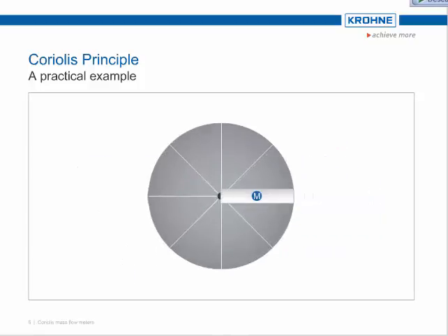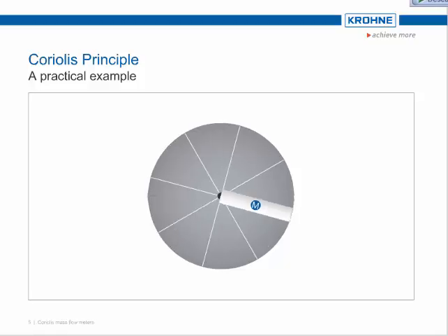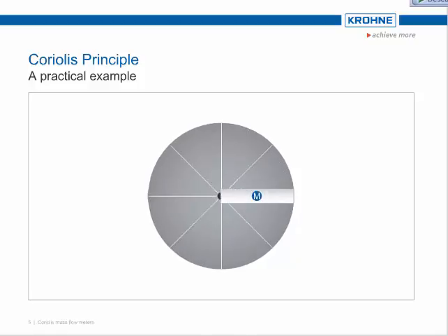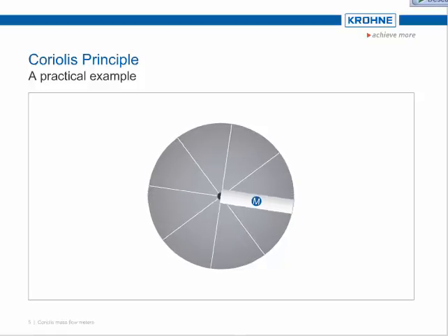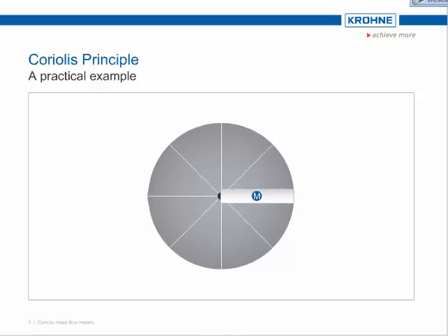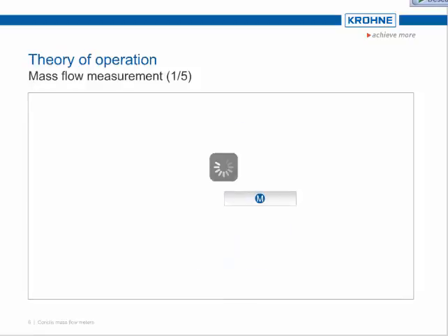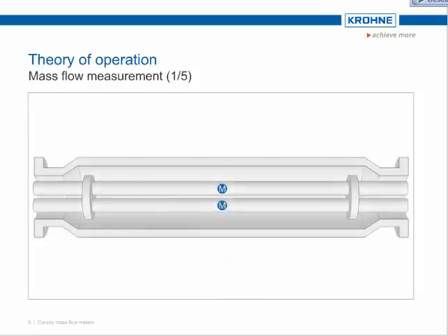A mass flowing in a measuring tube now replaces the ball on the carousel. The tube can rotate clockwise, or the tube can rotate anti-clockwise. If we reduce these rotations from full rotations to small angular changes, we can oscillate the tube through very small angles of rotation. These small oscillations are the principle used by the Coriolis mass flow meter.